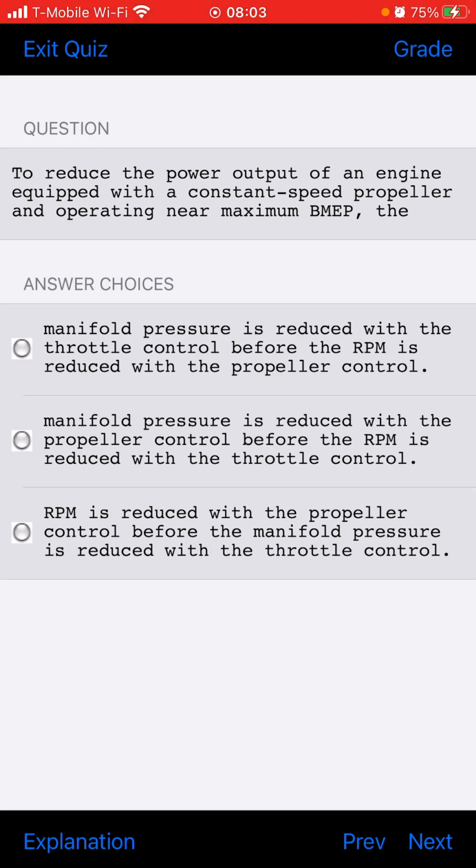When a radial engine has been shut down for more than half an hour or so, it should be checked for a liquid lock, by pulling the propeller through in the direction of normal rotation by hand for at least 2 complete revolutions of the crankshaft. If oil has collected in any of the lower cylinders, the spark plugs must be removed from these cylinders and all the oil drained out.